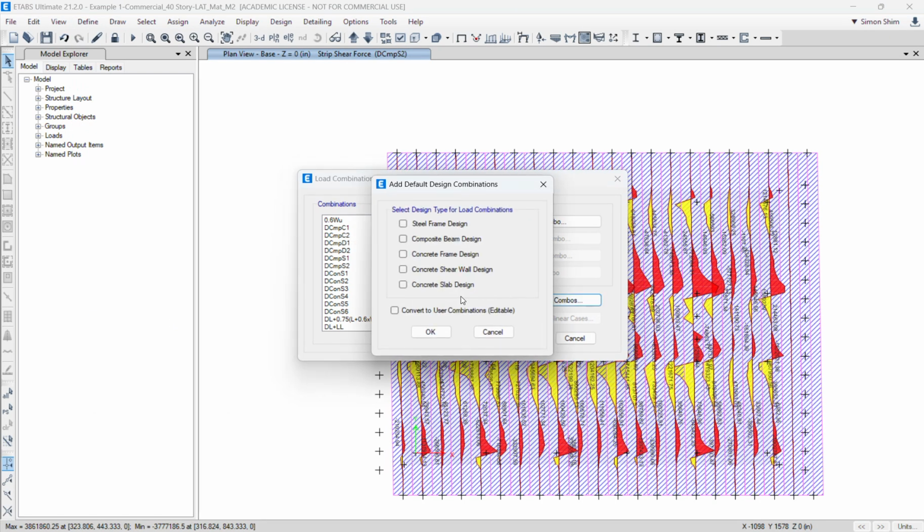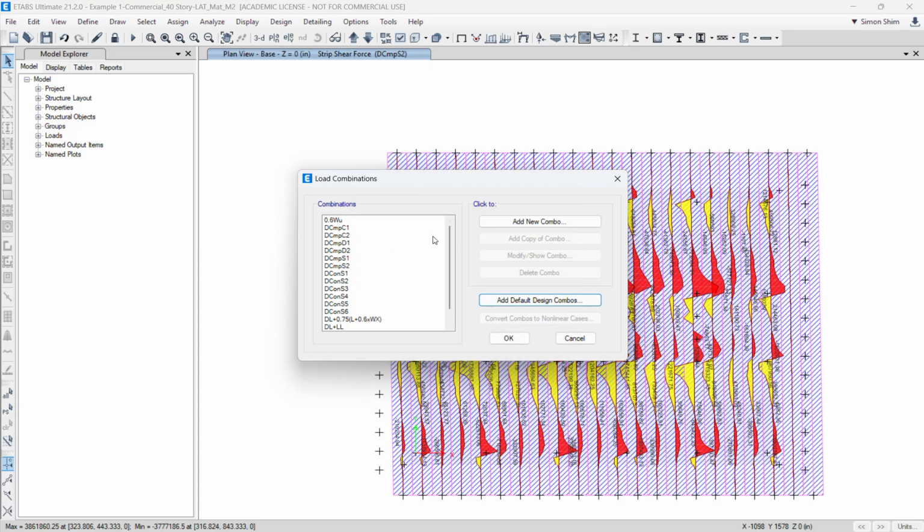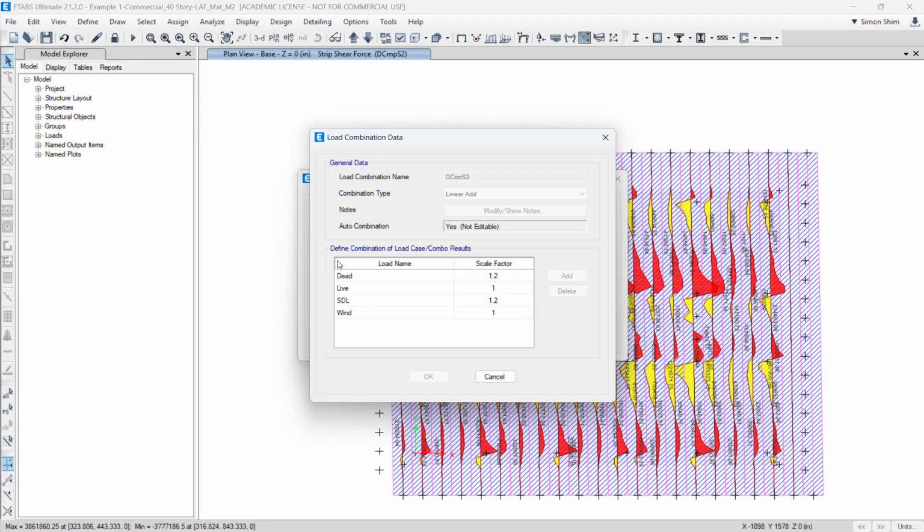But one thing I want to point out: since my ETABS has a good tool, it automatically sets up this design load combination with a properly established load pattern. This is actually quite efficient and time saving, but if you have another load case, it will generate another type of load combination with the service wind loads.